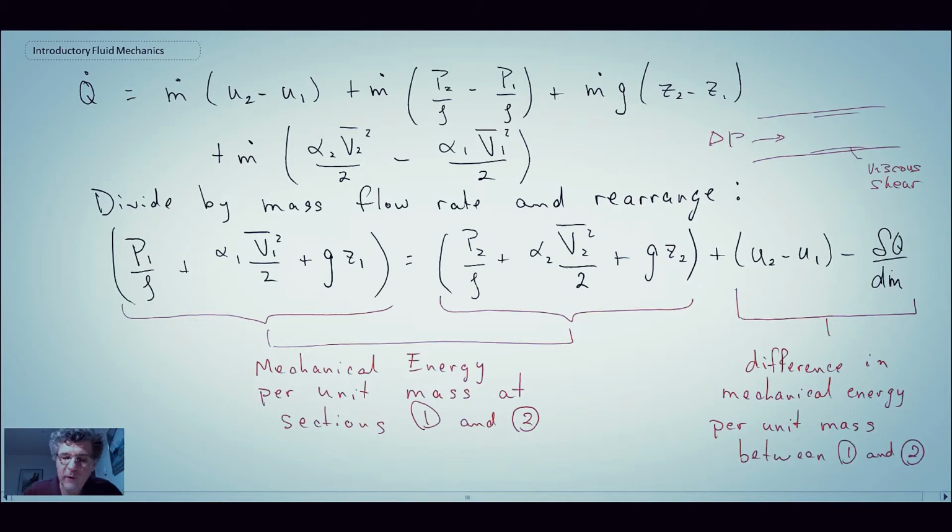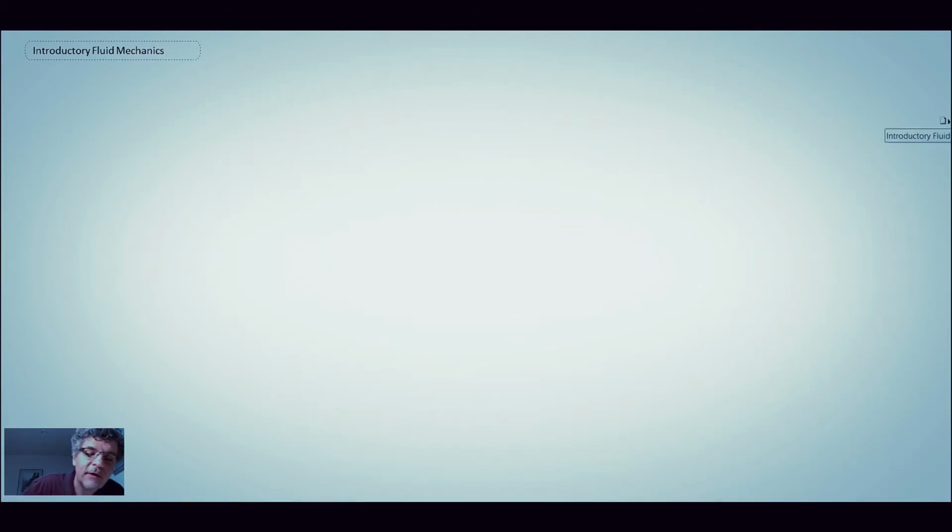So we know the mechanical energy is dropping, and the place where it is going is into increasing the temperature of the fluid, and that is an irreversible process. Once thermal energy is formed, kinetic energy is converting into thermal energy through viscous shear. It's pretty much impossible to get back unless you put a heat engine in there, and you're dealing with such low temperature differentials that that's the stuff of science fiction.